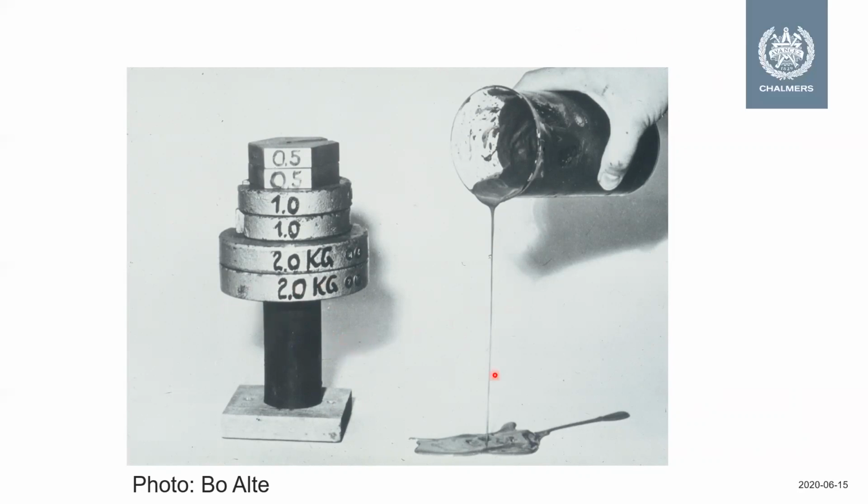But if you disturb it, it becomes liquid, with the consistency of Guinness. And these sort of clays are called quick clays or sensitive clays. So when I'm talking about the clays in Scandinavia, pretty much all clays in Scandinavia are clays of medium sensitivity. Due to the deposition process in a salty environment and the subsequent leaching, they tend to have a sort of structure so they yield at a higher stress level than they should. They have higher strength than they should, but when disturbed, they become liquid.